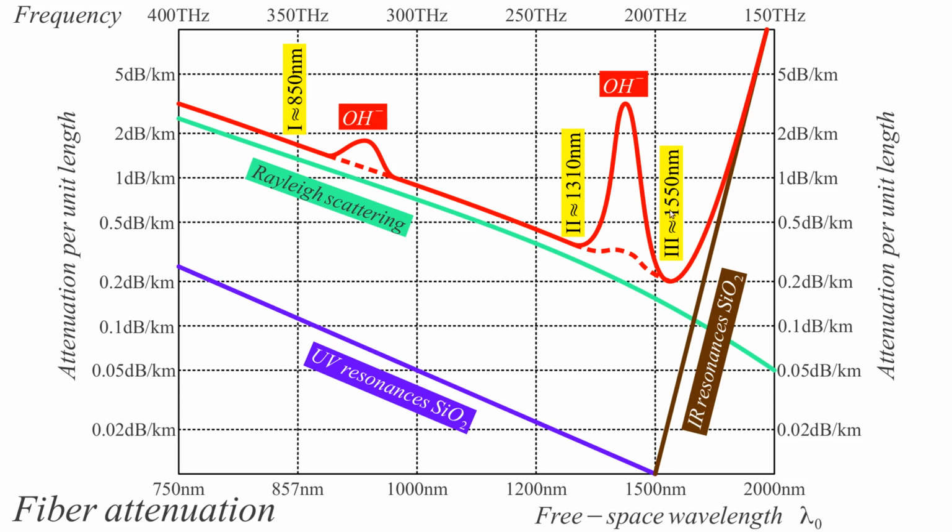And finally, communications moved to the third window, around 1550 nanometers. Again we have compound semiconductors, both for the laser and for the photodiode. Germanium can be used here, but it is not very sensitive, so it does not have very good performance here. So we have to have compound semiconductors. It was only around the year 2000 that communications moved here. So this is 1980, 1990, and 2000 that optical communications made it here, with the minus sign on the attenuation, of course.